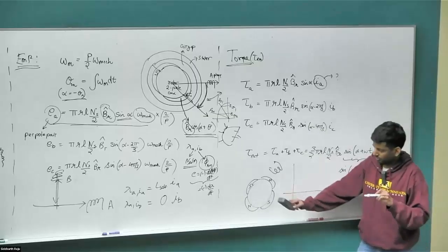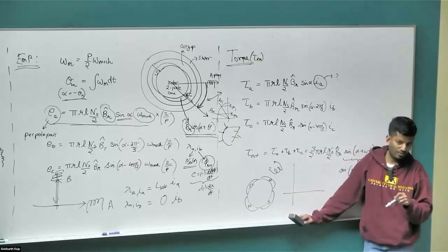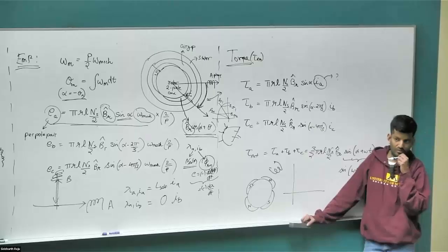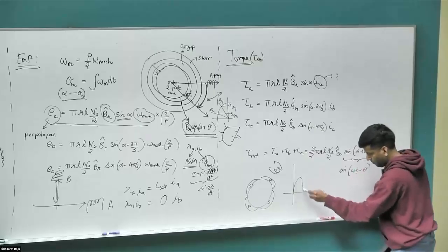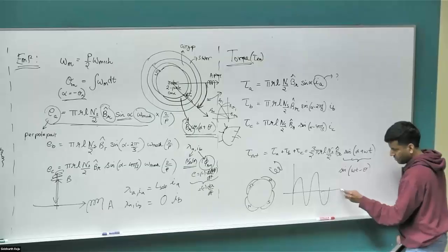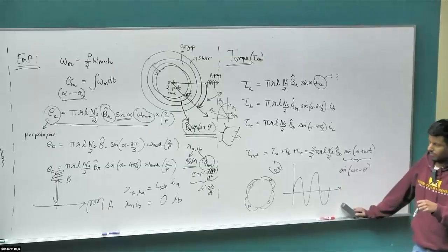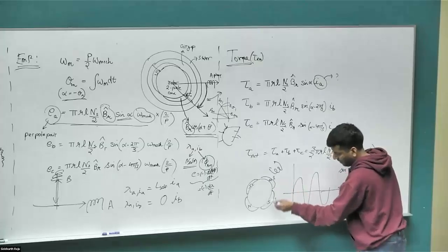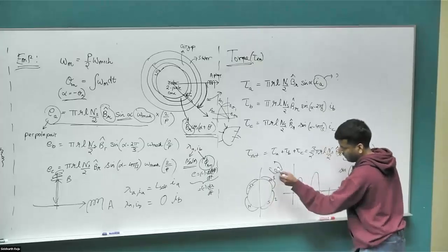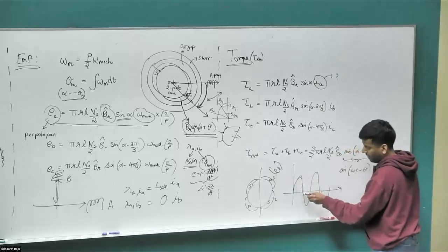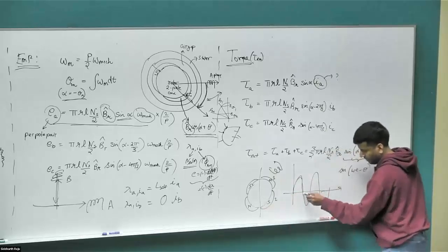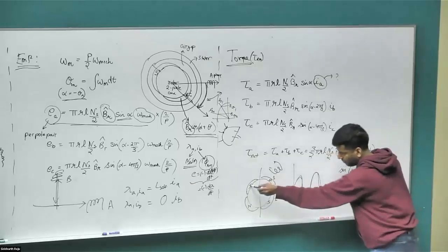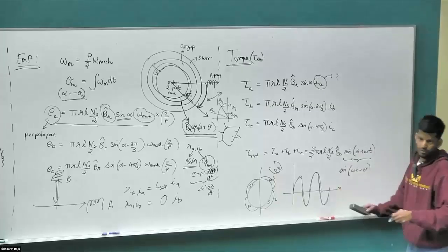If this rotor completes a full 360-degree turn, what will be the number of sine waves that are created? Would it be 2? Two. Perfect. Thank you. You would end up with 2 sine waves because at the start this is a north pole and then a quarter turn later, it becomes a south pole. So it'll go from positive, come back to 0, and then do the other quarter, and then from here to here, it'll do the other quarter.